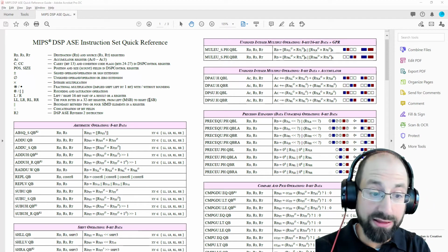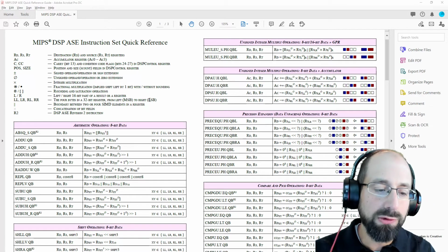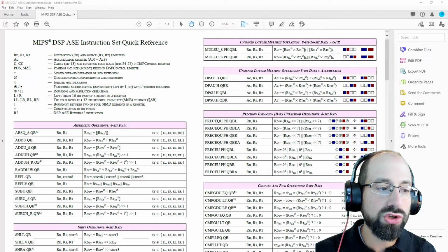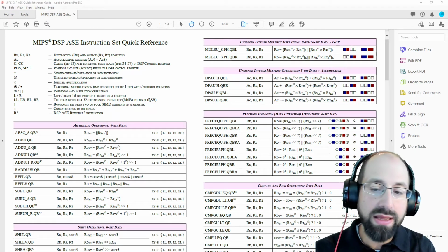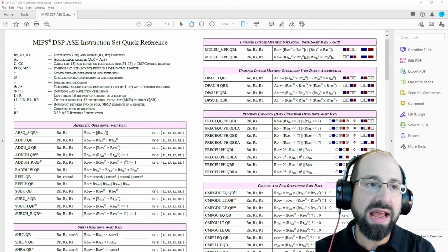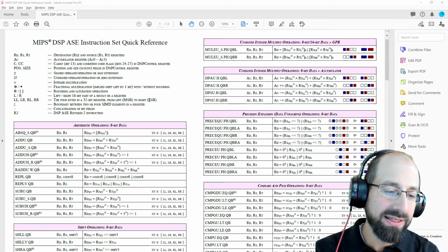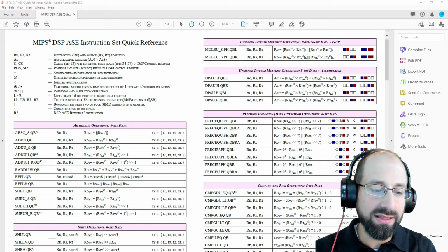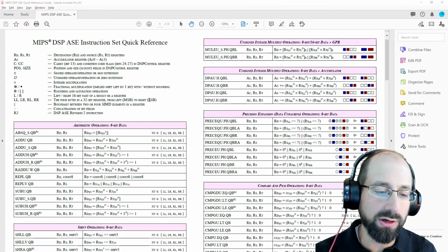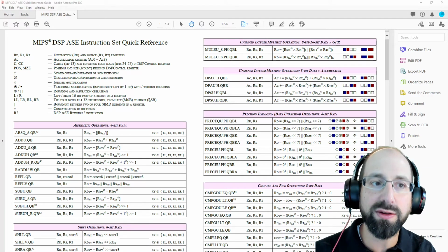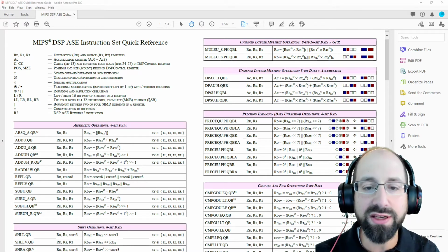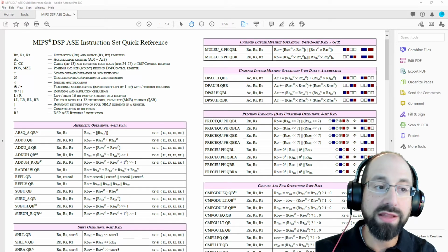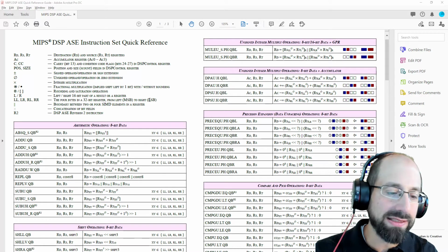Again, that's in theory 4x parallelism, where for a single instruction, we've done 4 additions with that addu.qb instruction. So in theory, we're getting a 4x speed up. It only works if our program has a need to do 8-bit addition, if our data fits into that type. If our data values are 22 bits wide, or that's the precision that we need, none of this is really going to work for us. Or we have to explore some accuracy and performance trade-offs of our code and try to shrink data down to fit into this format. But for code that is effectively just 8-bit arithmetic, these are pretty powerful instructions because they're allowing you to do 4 things for every given instruction.